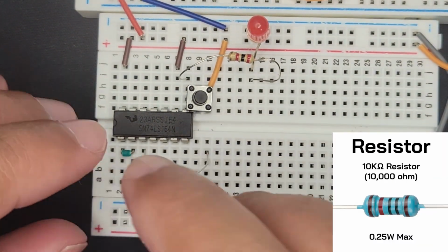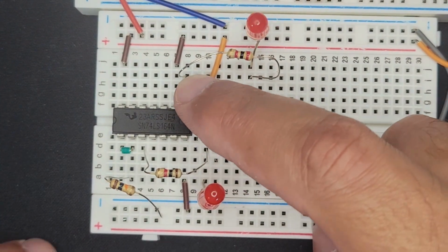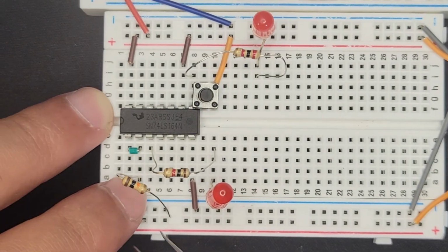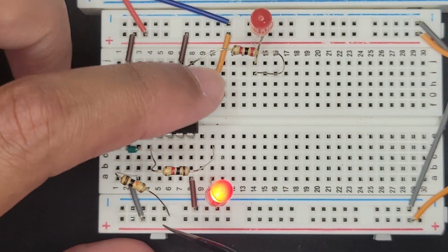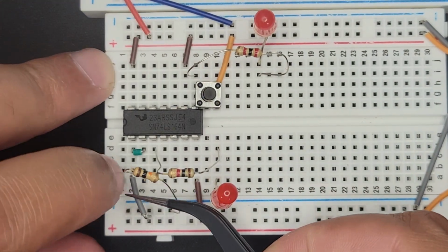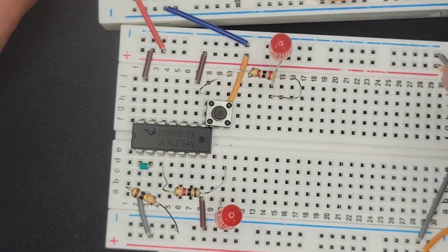So I'm gonna pull this one down, and then let's get our input back in. So right now it should stay low because it's being pulled down. But if we put the input back in, I'll use a small cable here, then it does seem to work. So A has a 1 right now, and then A has a 0. So it's working to get the input in there. However, it doesn't seem to work with the astable multivibrator.